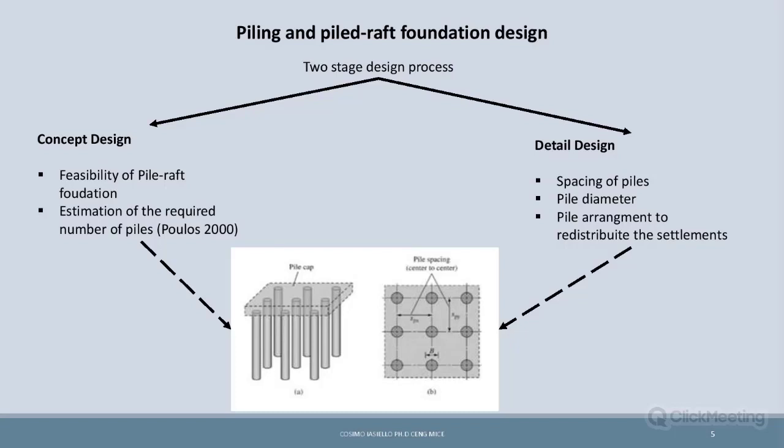So the interaction between the piling and the slab is a pure interaction regarding the yielding of the soil. If this is the case, there are some analytical and closed form calculations. Some of them are collected in the standard of Hong Kong regarding piling, but my personal advice is to carry out a numerical analysis.